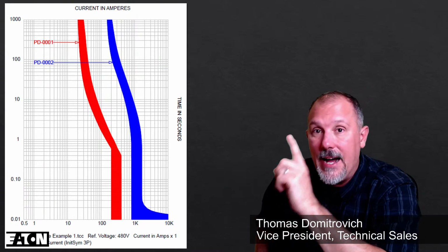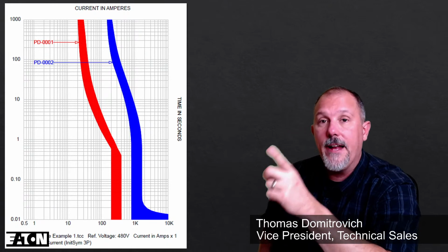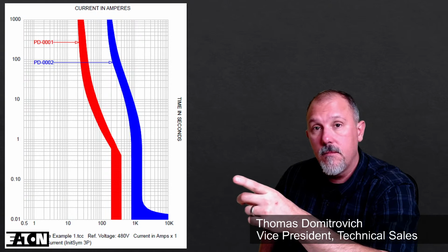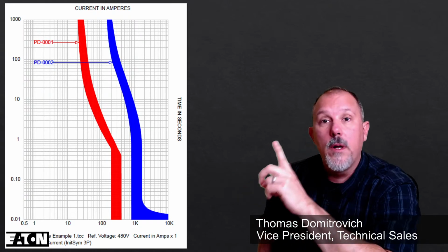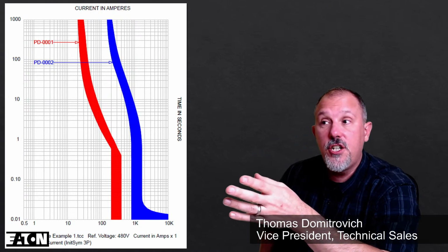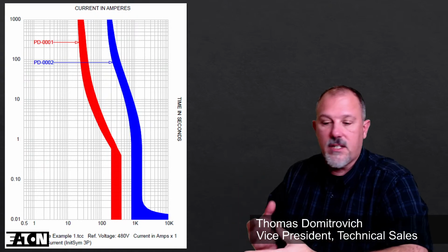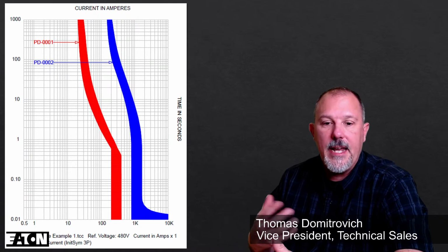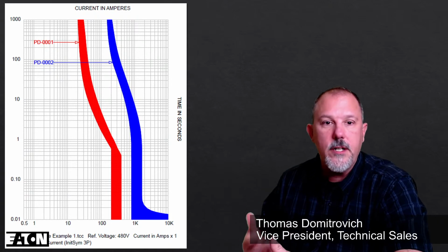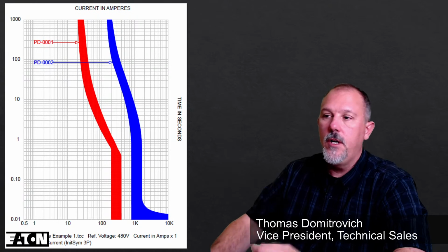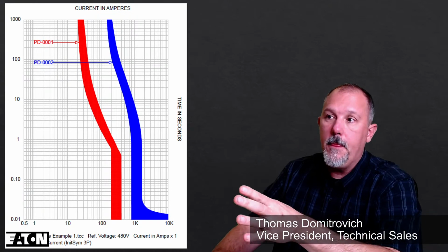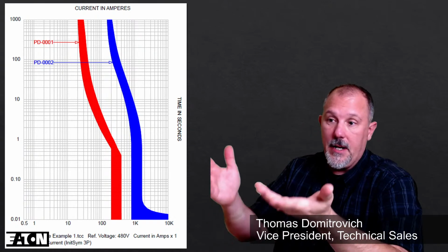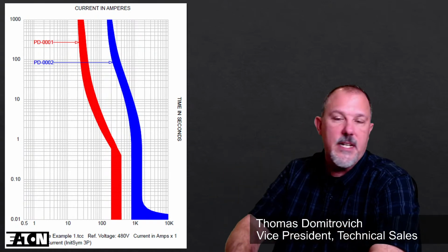So that means that I am able to open that red BAB 30 amp circuit breaker faster than one cycle. And that's sheerly because it's such a small breaker. The physics, the mechanical nature of it, opens it really doggone fast. So from a coordination perspective, I go all the way down. I have separation all the way down to 0.01 seconds.